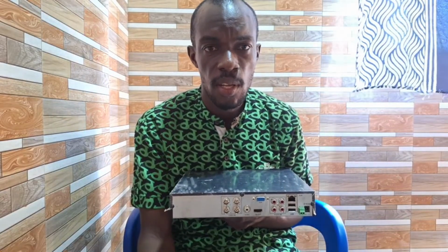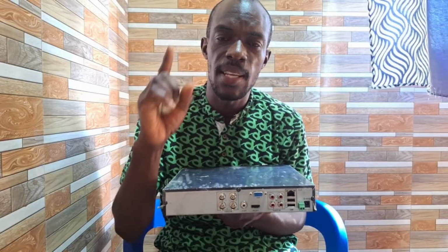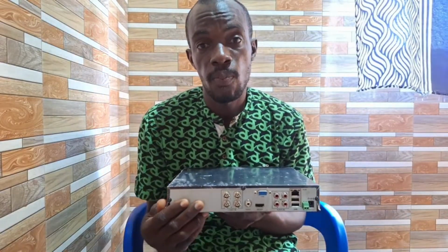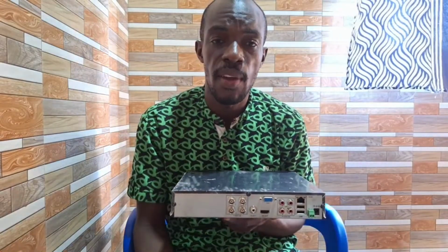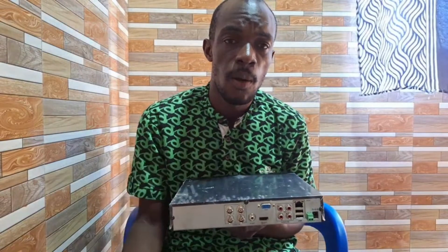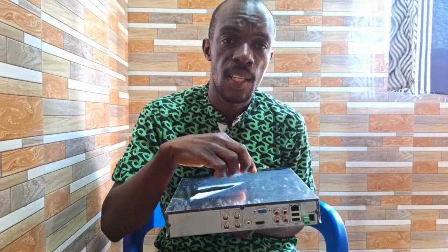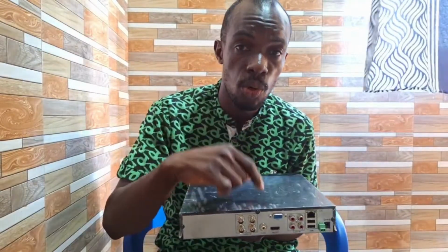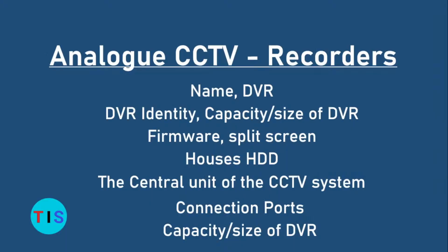If you want longer duration, you cannot just take any size of hard drive. The manufacturers of the DVR have a specific limit, which you can find in your DVR manual, that tells you the largest size of hard drive. Refer to your manual to know the size of hard drive you can install in your DVR. But I assure you, in the next lesson I will show you how the hard drive is fully installed into the DVR.